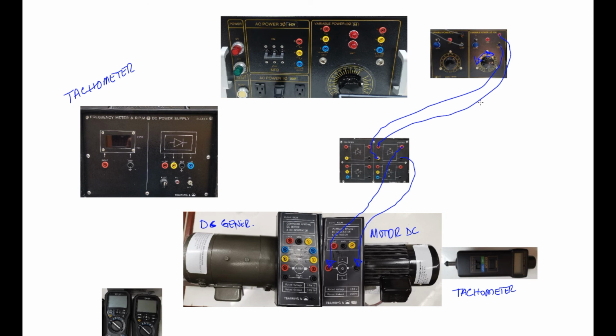Now we have excited and supplied our motor. As soon as we start our source and keep on varying the voltage toward the maximum, for example, the motor will rotate. We stop when we reach the rated speed of the generator, of course.